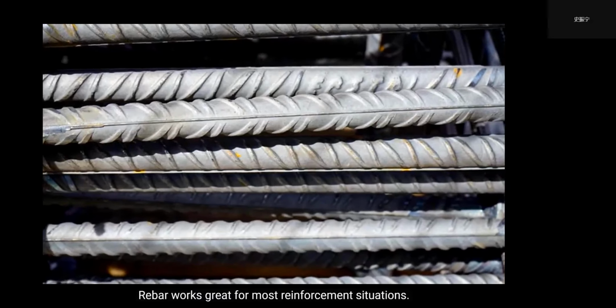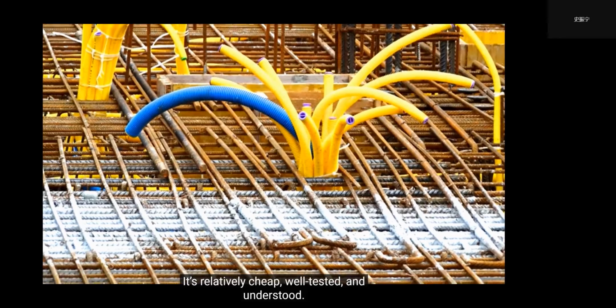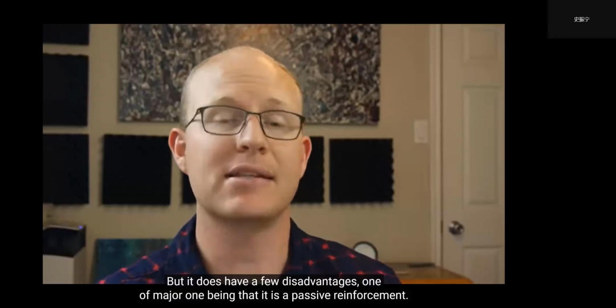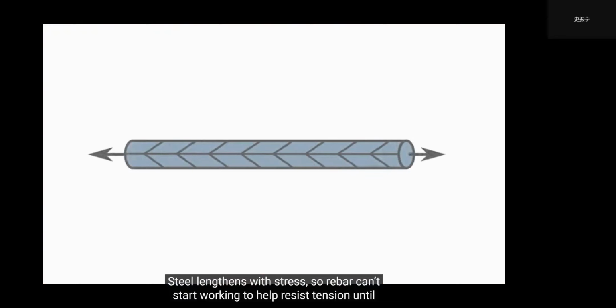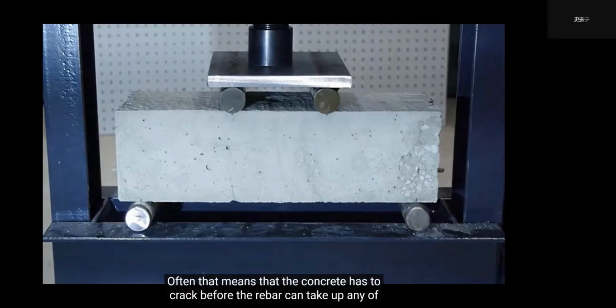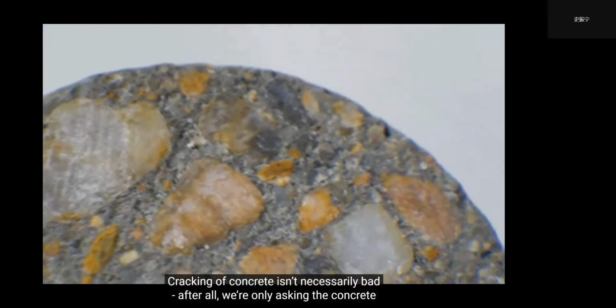Rebar works great for most reinforcement situations. It's relatively cheap, well tested, and understood, but it does have a few disadvantages. One of the major ones being that it is a passive reinforcement. Steel lengthens with stress, so rebar can't start working to help resist tension until it's had a chance to stretch out. Often that means that concrete has to crack before the rebar can take up any of the tensile stress of the member. Cracking of concrete isn't necessarily bad.